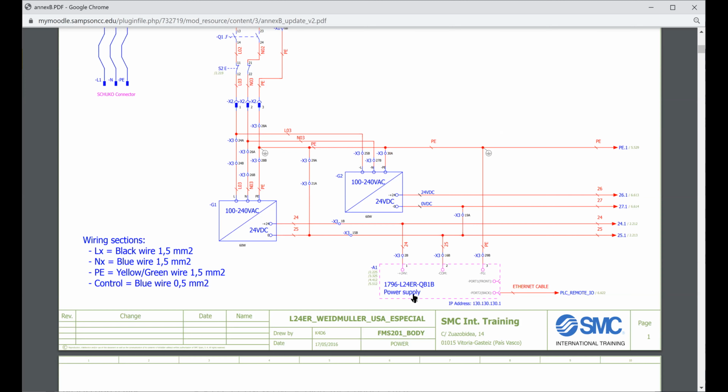Some PLCs are a mixture, like this one right here. This PLC has got AC cards and DC cards. Just so you know, don't think that every PLC system is like this. Slot 1 is the AC input, 16 AC inputs.